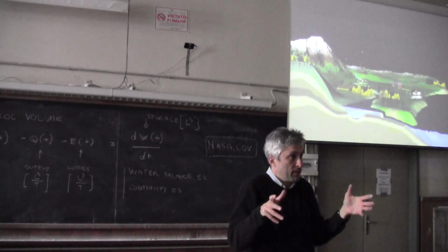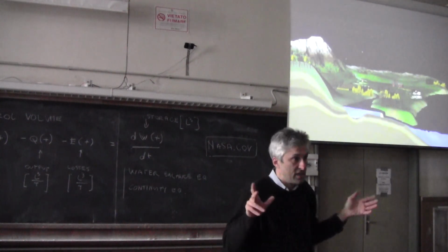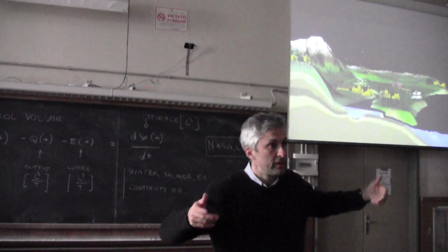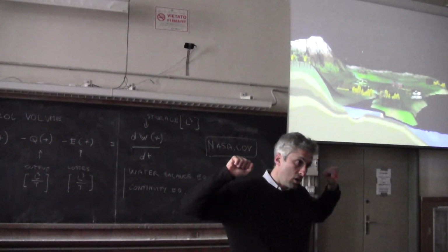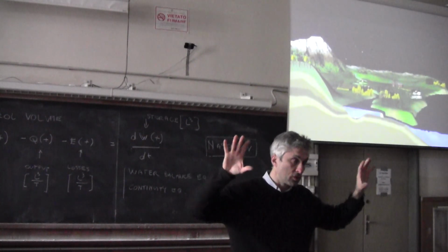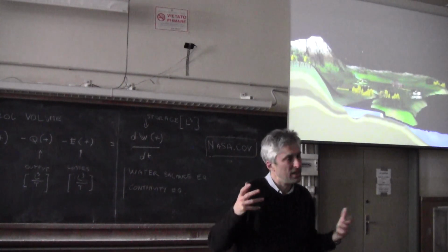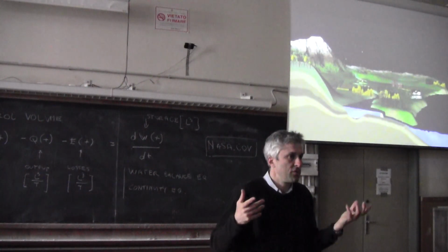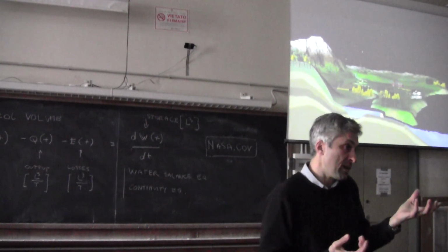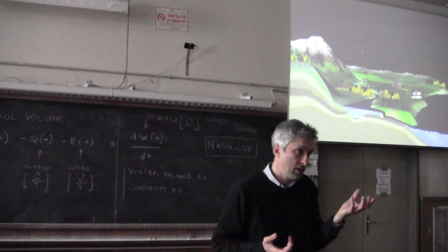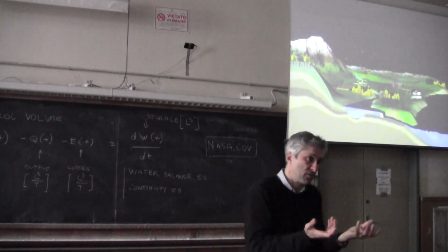But to describe this phenomenon, we can't do that, because we tried in small experimental basins. People dug some hill slopes in experimental basins, and they also provoked artificial rainfall to try to study how rain partitions, but the results of these experiments are contradictory. Of course, if you get a very impervious hill slope, characterized by a very low permeability, then you are more likely to observe surface runoff.